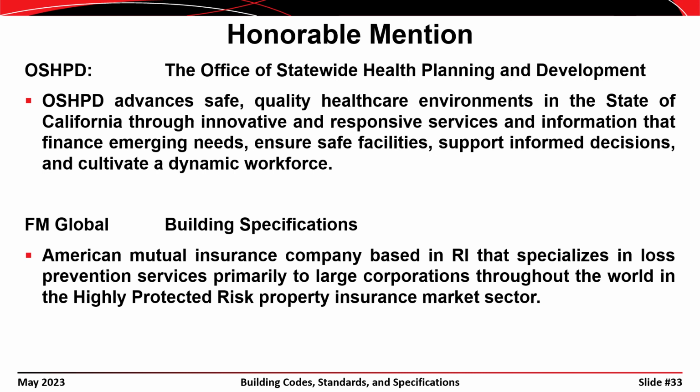It's expected that the building will likely sustain significant damage or be a total loss, but as long as no one is hurt, then the goal of the codes and specifications is achieved, even if the building is a total loss and it has to be destroyed several days after the extreme event. When an owner is investing millions of dollars in a building, they might want to have a higher level of performance out of their structure than just life safety.